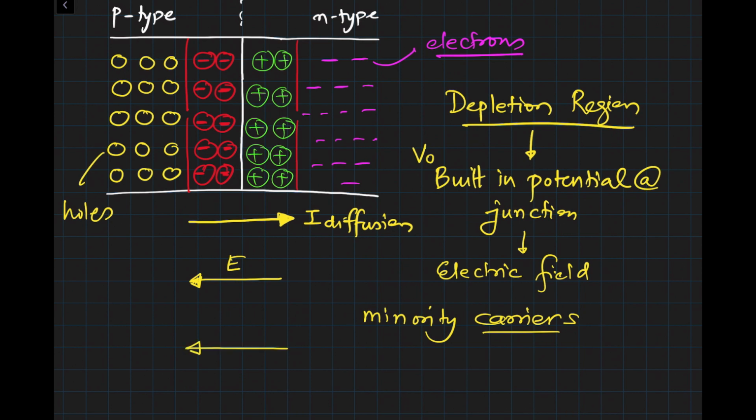So we will see something called drift current here, I drift. And as the name suggests, just like our paper boat will drift in a strong current of water, in this particular case, the minority carriers will drift in the existing electric field, which has happened because of these other things. So at equilibrium, we say that I diffusion is equal to I drift.